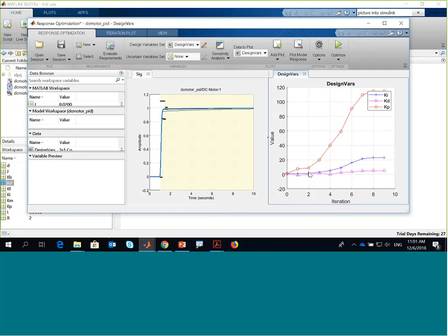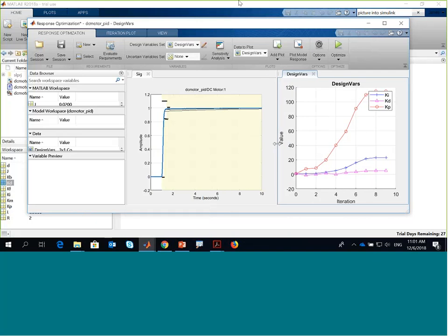I think that's also potentially what we would do on a real system. In normal control loops, usually you increase the KP up to a certain level, then you want to minimize the error, so you increase the KI. And then the error goes to 0, and then you look at the response, and maybe you play with D a little bit. Very nice, very powerful.